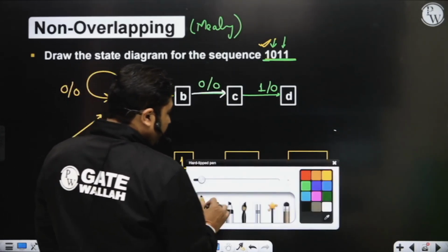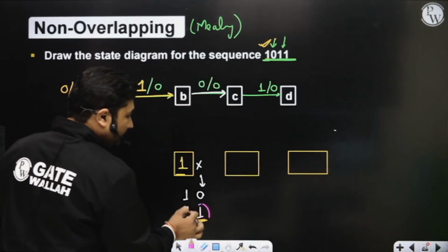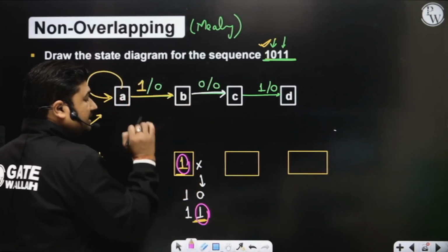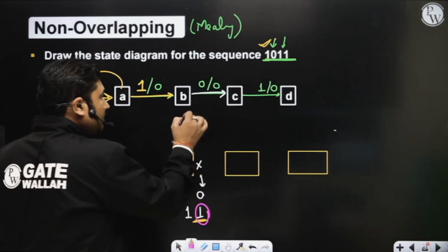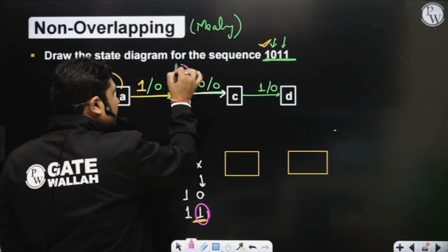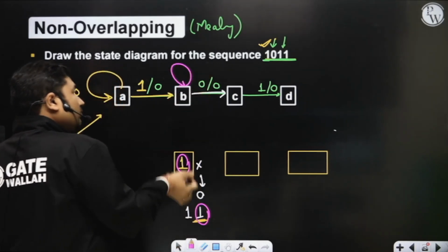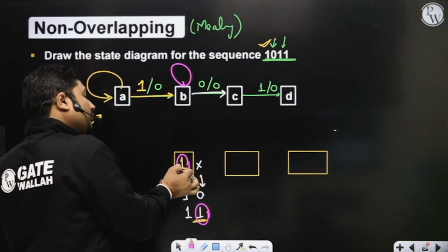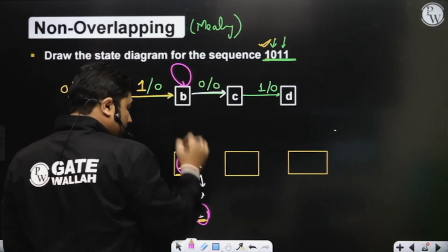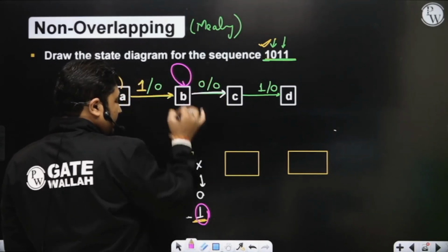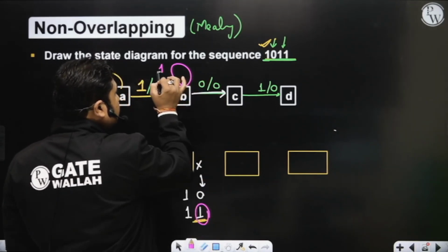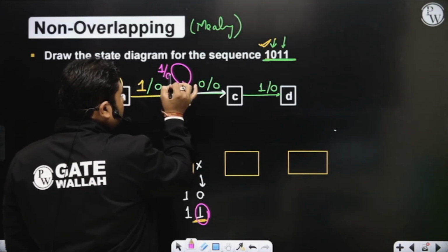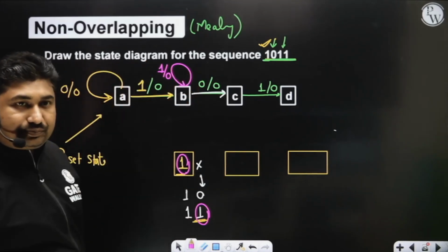If the last 1 bit and the 1 bit position are the same, then stay in the same state, otherwise move to the reset state. So since the last bit equals the 1 bit state, stay in state B only, and this appears when x equals 1, sequence not detected, so output is 0.